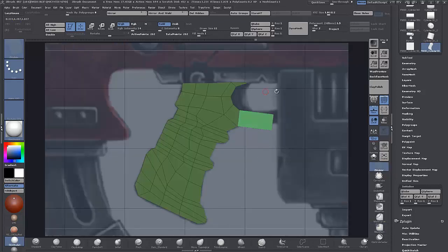So we're going to be back to using our transpose move, because we've obviously added some thickness, so we can't just move the verts around. But I find that's the way I would be doing it if I was modeling traditionally in 3D Max or something. I'd be edge modeling, but you can't really edge model in ZModeler, it's a box modeler. So it's just a good way to maybe get a shape like that and get your topology laid out in an edge modeling fashion, and then you can extrude out.